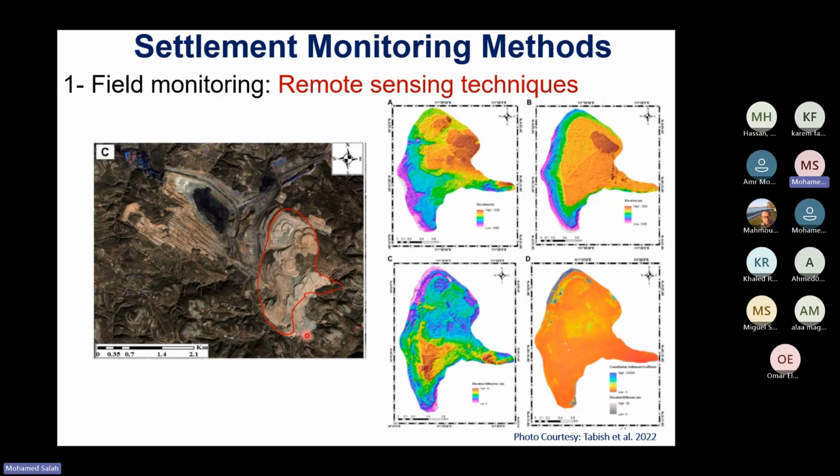Then we adjust the coordinates of the photo and we start to draw longitudinal or horizontal sections that show us exactly the topography of the ground. The advantage is that from time to time you can just use this drone surveying to survey the whole area, and this is very effective if the site is not easy to access.